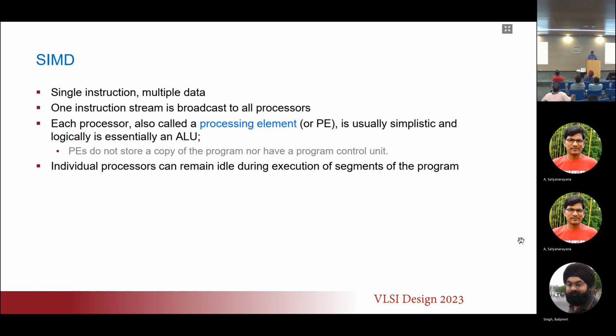And then we have SIMD. SIMD is very interesting because that's where a lot of the companies are focusing these days. We have single instruction and multiple data. What would be the benefit of having single instruction and multiple data? Let me give an example. When you have this convolutional loop, inside of the loop, to do a multiply and an add, you have to fetch the multiply instruction, you have to fetch the add instruction, and you have to write it back.